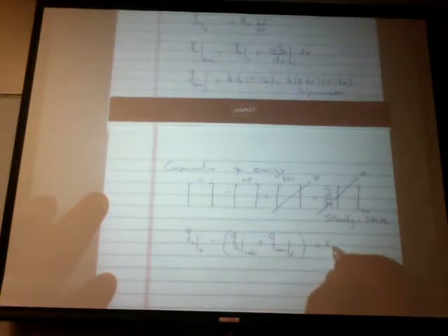So basically, in is Q by conduction at x, out would be Q by conduction at x plus dx, plus Q by convection at the periphery. And that's equal to 0. And at the end, the equilibrium equation, if we plug in all these values, will be d/dx of k times the cross-section area to which conduction takes place times dT/dx, minus h p, that's the perimeter, times (T minus T infinity), is equal to 0.